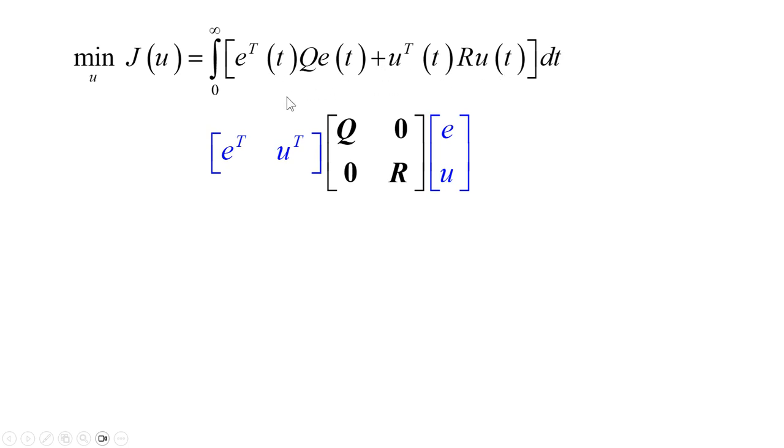We can visualize Q and R as parts of one larger block diagonal weighting matrix. While you could fill in the off-diagonal blocks to penalize cross products between states and inputs, we often keep things simple and set those to 0. So, our design focuses entirely on tuning Q and R.